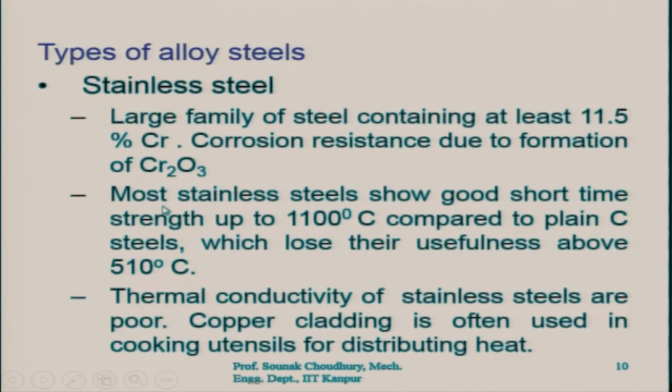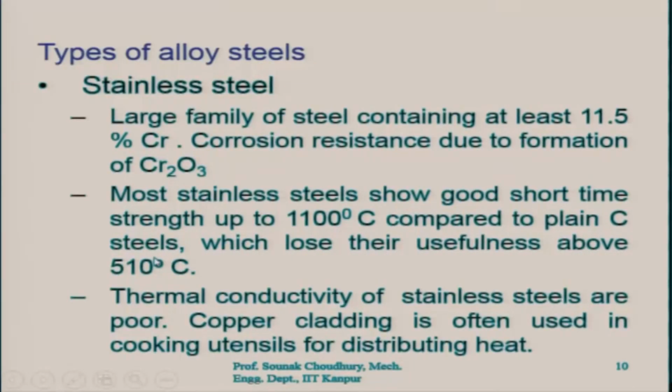Most stainless steels show good short time strength up to 1100 degree centigrade. So, it is a very high temperature, by the way, and even at that high temperature it will retain the strength for a short time. After the temperature is increased further, the strength will be less compared to plain carbon steel, which loses its usefulness above 510 degree centigrade.